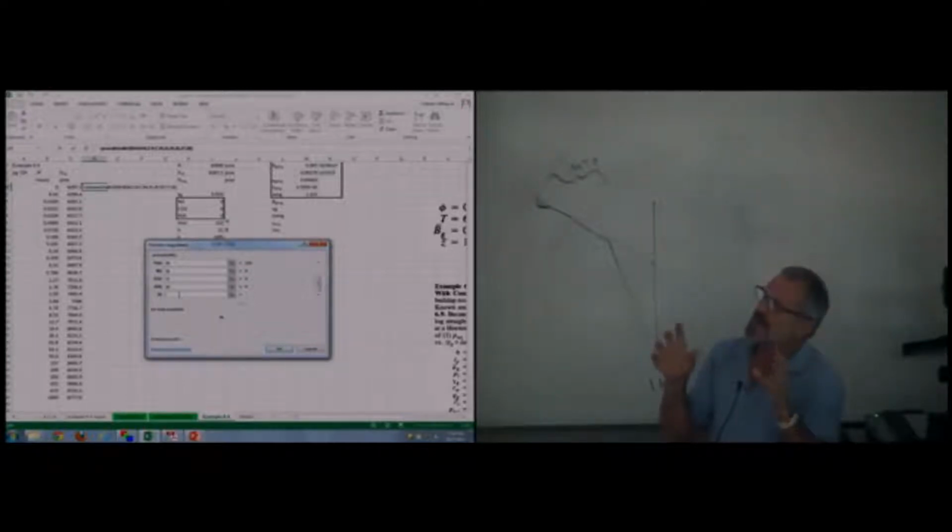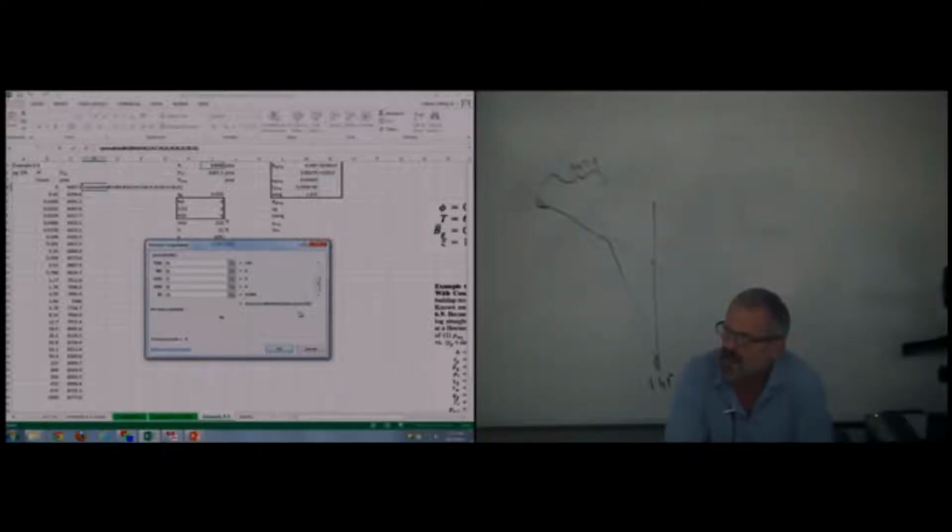It's not required to calculate pseudo time to use initial pressure, but to calculate pseudo time apparent, I'm going to calculate pseudo time, and then I'm going to multiply it by viscosity and compressibility at initial conditions, and so I get an apparent viscosity and compressibility. It's not going to really change my analysis. Okay, and you can see in the dialog box down there at the bottom, I'm not just going to get one number, I'm going to get a bunch of numbers. I'm going to be able to fill in this array.